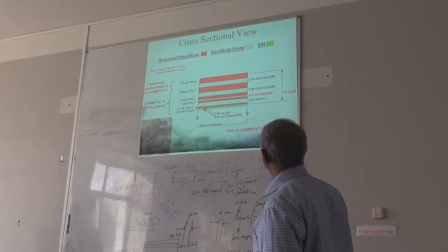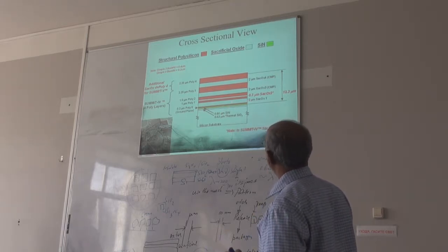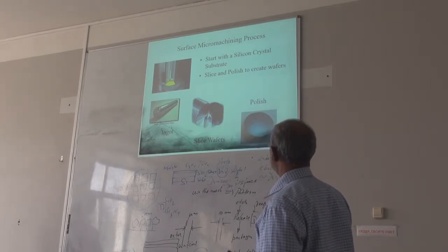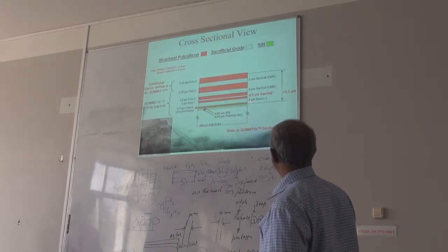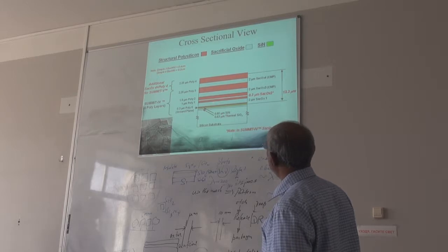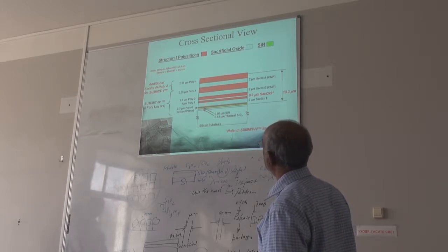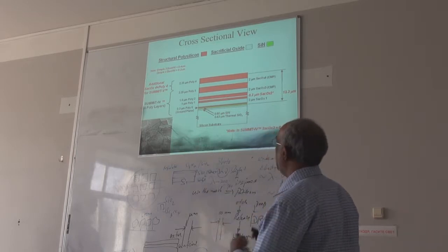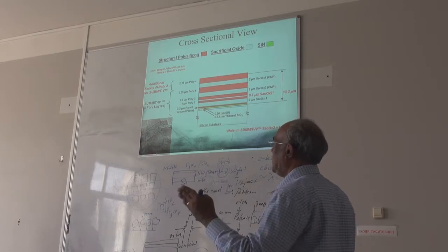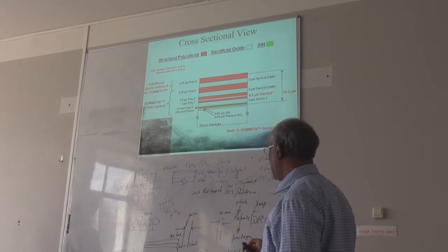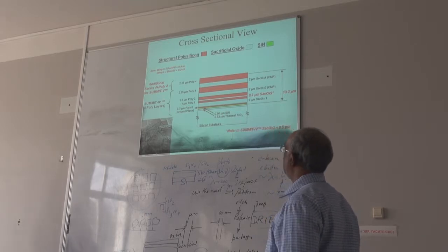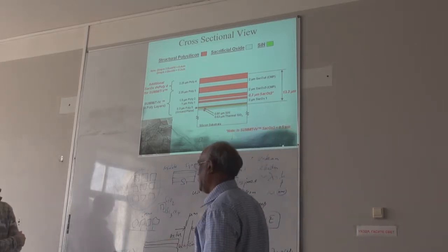If you want to continue, you can put another sacrificial layer and then another functional layer, polycrystalline, then another sacrificial layer, and you can heat at any time you need. At the end you can etch it and release it. Then you can make structures like these. We will get into details like this.